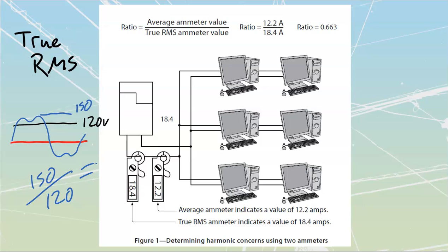Now, in some cases, if you don't have a good quality meter, it's going to be difficult to do this. You're also going to have to do this while the system is live, measuring these voltages. We're allowed to measure voltages live. It's one of the things we are allowed to do. But you're just going to have to be careful, use proper PPE and everything else as part of that. In some cases you won't necessarily see it on the voltage, you will otherwise see it on the current. Remember that harmonics can be either harmonic voltages or harmonic currents.